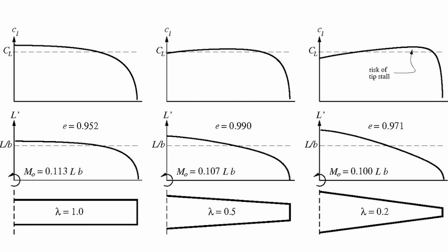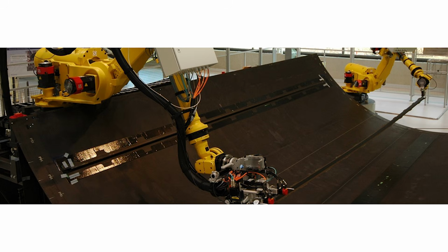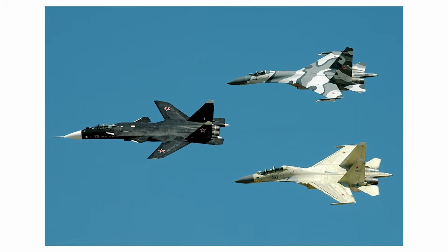With a tapered wing, the more complex shape also increases the manufacturing complexity, particularly with sheet metal. Modern composites have mitigated some of these issues, but the shape can still be challenging to make. For most applications, a tapered wing is ultimately chosen for its higher performance or load capability, despite the more demanding handling at high angles of attack.